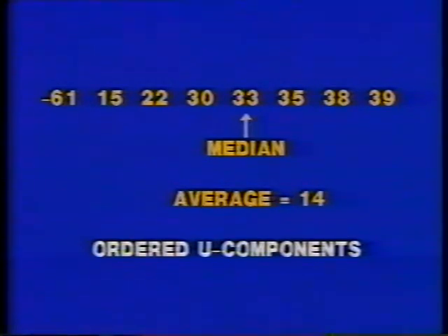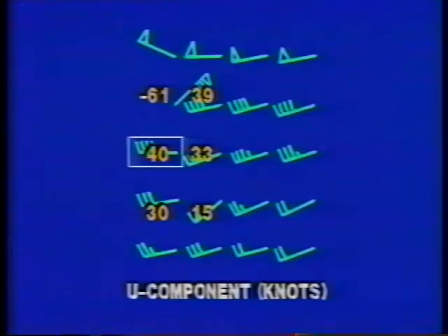If the difference for either component exceeds the threshold, the median is recomputed using data from just the current and previous hour. Maybe a significant wind shift occurred during the past few hours. If the difference from the median still exceeds the threshold, the observation, including both components, is flagged bad.